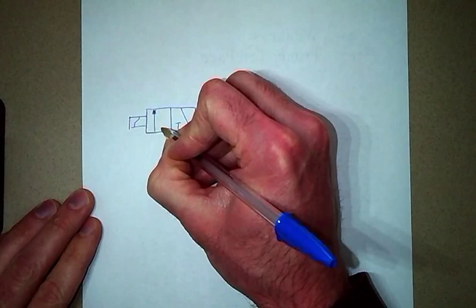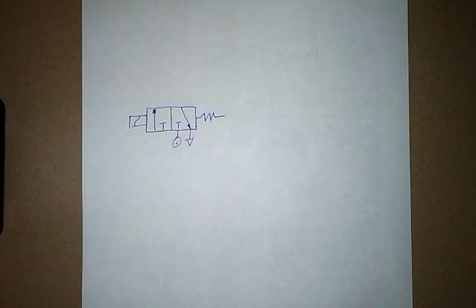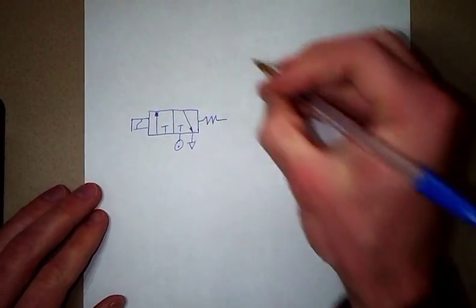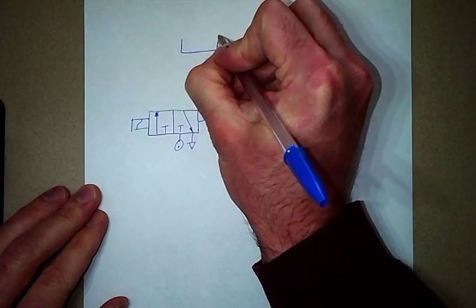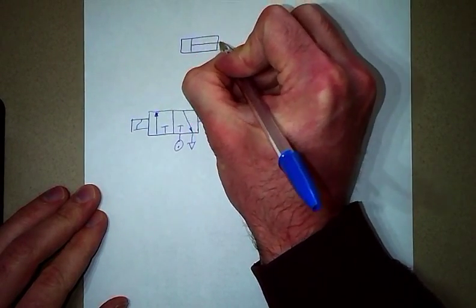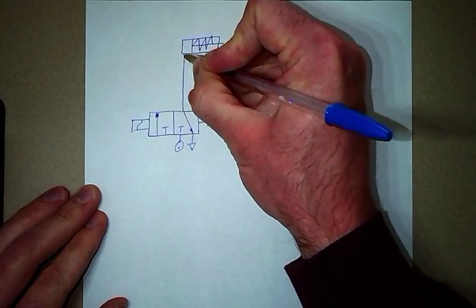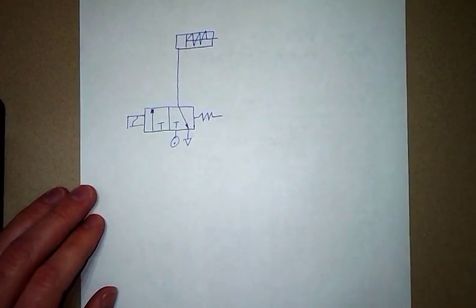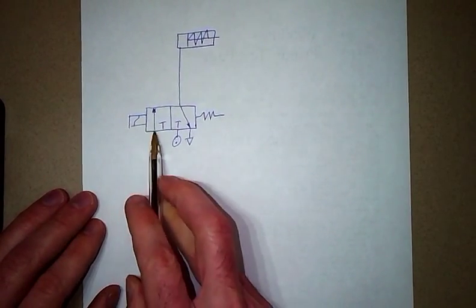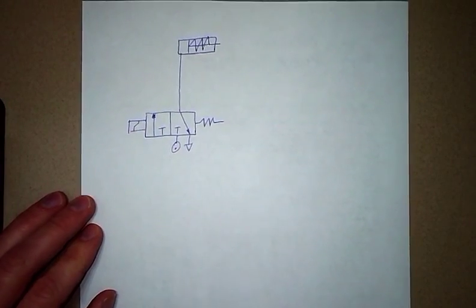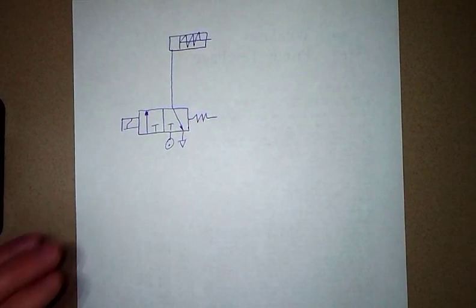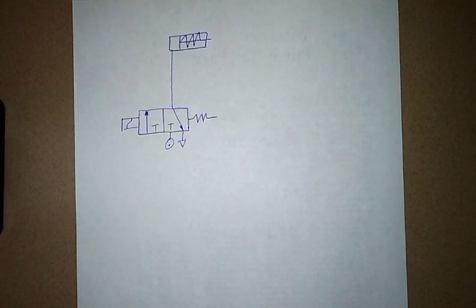So this is going to be an example of using electric systems to control this pneumatic system. Say we have our single acting cylinder up here, and it's the output for this valve. To extend the cylinder, we need to provide current to the solenoid on the valve, and we need to describe how current is supplied to that solenoid.